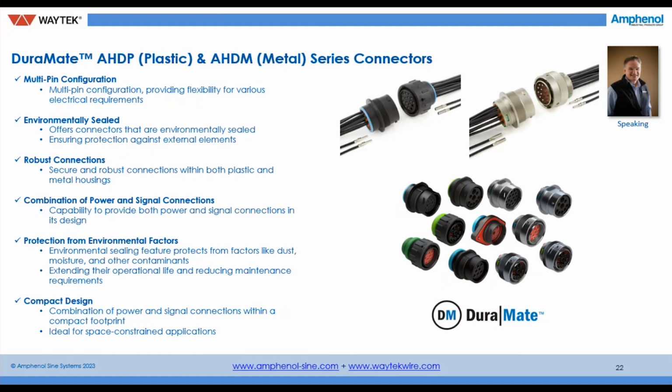The plastic, of course, is going to be lightweight. They're going to excel in ag. They're going to excel in saltwater environments. And in the metal connectors, using the same inserts, metal versus plastic, so they're interchangeable, just like the contact system. If it's a more robust requirement, if it's more heavy duty, if there's going to be some rough contact, such as forestry, or even in some of the heavy equipment applications, that metal is going to be a great alternative for you.